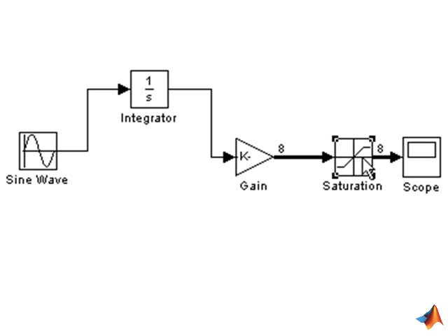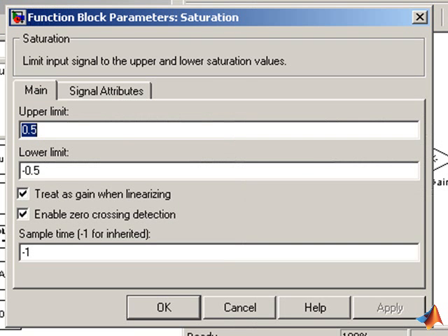Now, this is still fairly trivial, and I might make this a little more complicated by changing the saturation limits. So instead of using fixed saturation limits, let me use random saturation limits between -10 and 10, for example. And what I'm doing here is using the rand function from MATLAB to generate 8 random values between 0 and 1 and multiplying that by 10 to create the upper limits, or 10 random upper limits, and doing the same thing to create 8 random lower limits between 0 and -10.